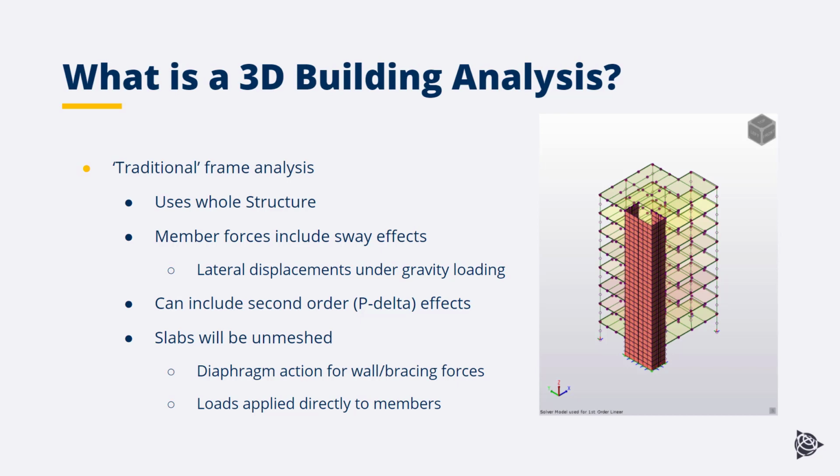If we're looking at a floppy frame system, these second order effects can represent a large increase in the design forces calculated by the software, so having an analysis in which these can be considered is important for the design of the structure.